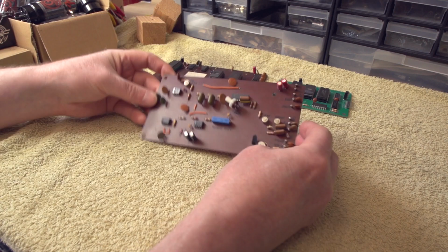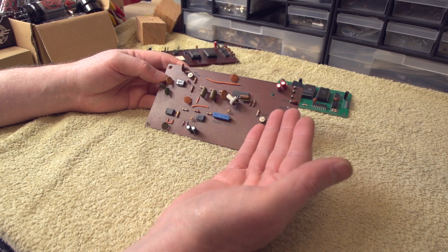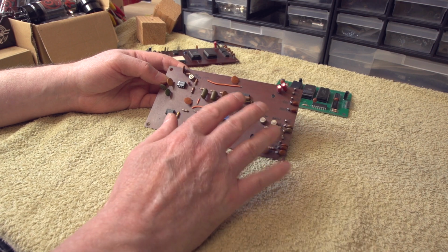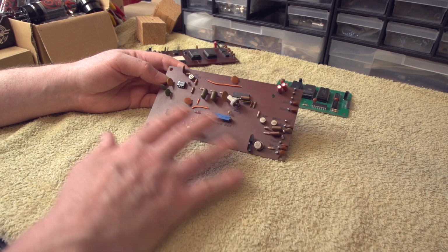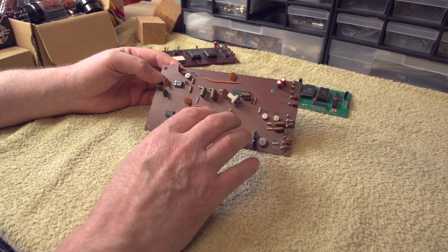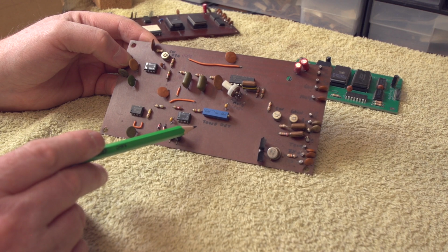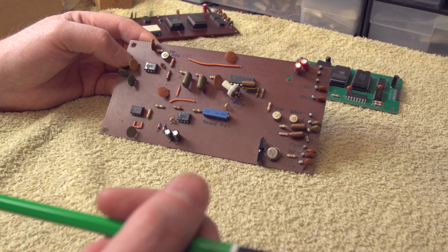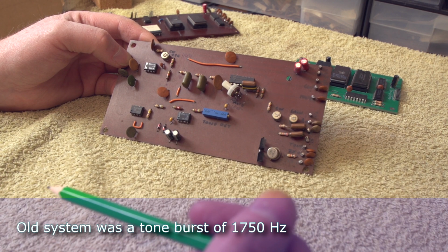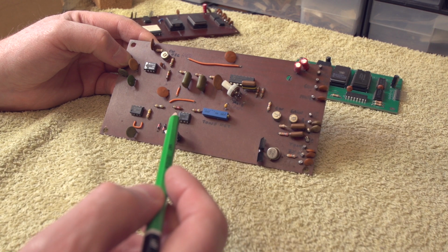As far as the audio card goes, on this card you've got various circuitry to take care of the analog signals from the radios, both on the receive side and on the transmit side. And this basically, if you like, is an audio interface which connects the two radios together. Now, back in the day, repeaters used to use a tone burst to activate the repeater. Without that tone burst, the repeater wouldn't switch on, and it was a safeguard against spurious noises that might be picked up on the band, or other radios that don't have a tone burst fitted. You may not want them to activate the repeater for whatever reason, so you would use a tone burst.